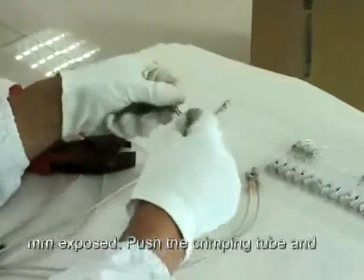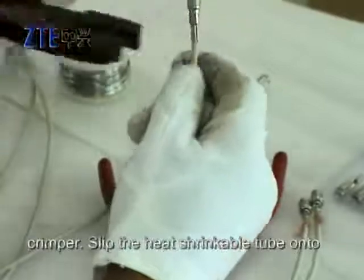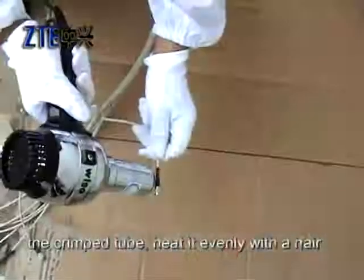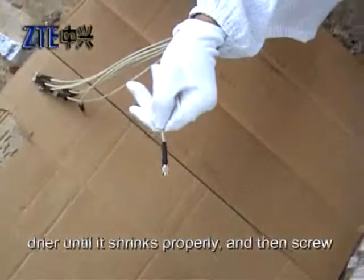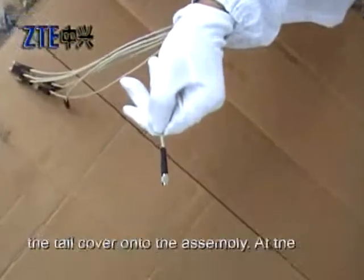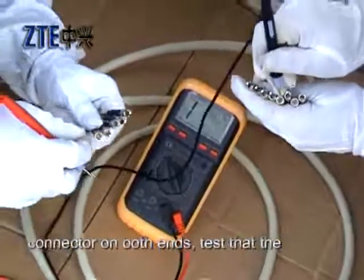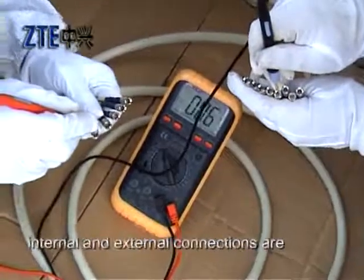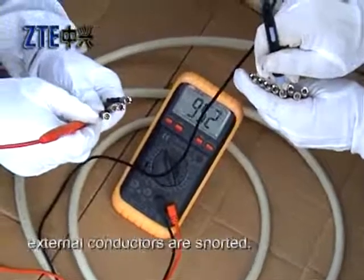Push the crimping tube and shielding mesh together into the rear of the plug. Press or clamp the tube with a wire crimper. Slip the heat shrinkable tube onto the crimp tube, heat it evenly with the hairdryer until it shrinks properly, and then screw the tail cover onto the assembly. At the connector on both ends, test that the internal and external connections are conductive, and that none of the internal or external conductors are shorted.